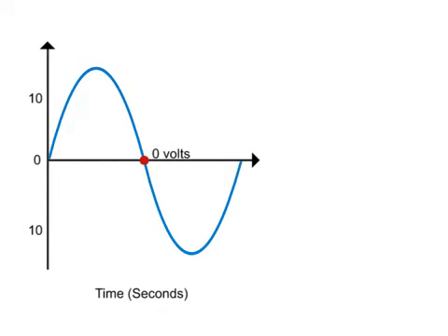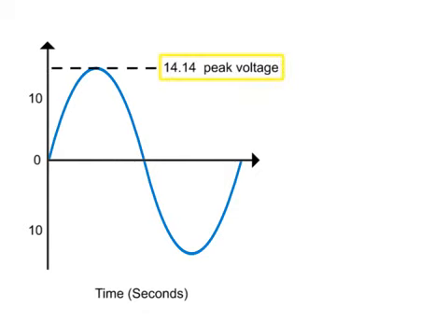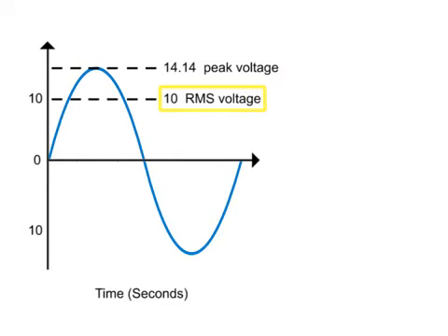Thus, on average, full voltage is not being continuously delivered to the AC circuit to generate the same power as a DC circuit. Therefore, to compensate, AC circuits need higher voltage input. When the power in the DC matches the power you produce in the AC, a voltage of 14.14 volts at its peak is as effective in producing the same power as 10 volts in a DC circuit.